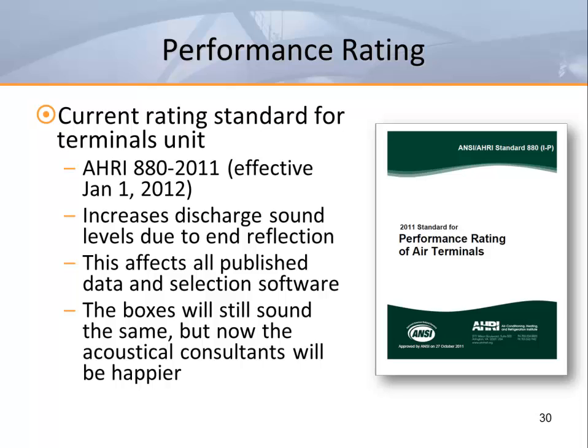This will effectively increase sound levels on all types of terminal units, with the most effect on smaller units. This happens because the smaller the discharge duct is, the greater the end reflection will be. Larger units will see little to no change.